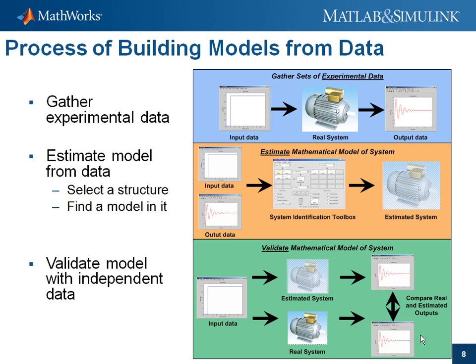The graphical user interface, the GUI, may provide a good guide through this workflow. Finally, validate the model by confronting it with independent data sets. In that way, we are assured that we have not overfitted the data to the artifacts of a particular data set. I may add that in this process we do not only get a model of a system, but also some indications about how reliable it is. We get measures of the uncertainty of a model as well as how much of the output is affected by its disturbances. This may be quite useful, for example, for robust control design.